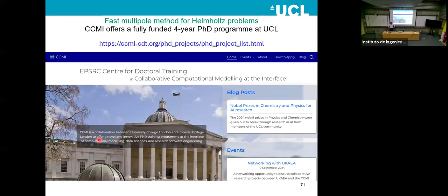In terms of taking into account the heterogeneity of the skull, that's challenging because what comes out of your MRI scan or CT scan is generally of resolution of 1 millimeter voxels. You need to mesh at sub-millimeter levels to correctly predict what's happening. And so by doing so you may actually be introducing more uncertainties and assuming homogeneity. This is work in progress.